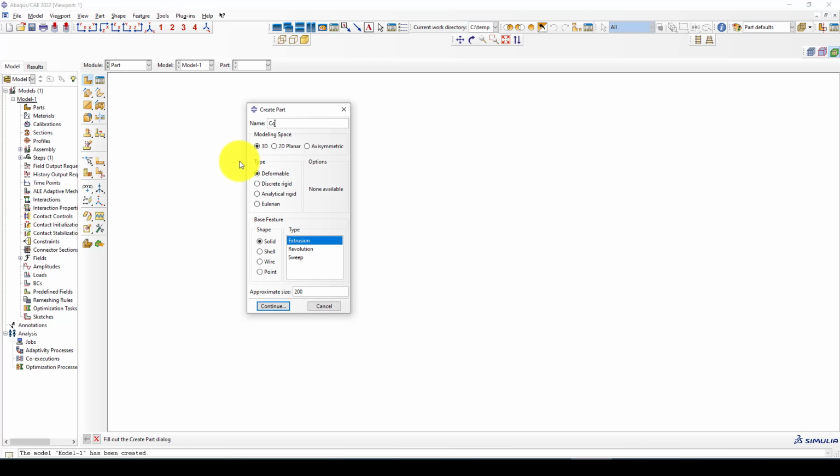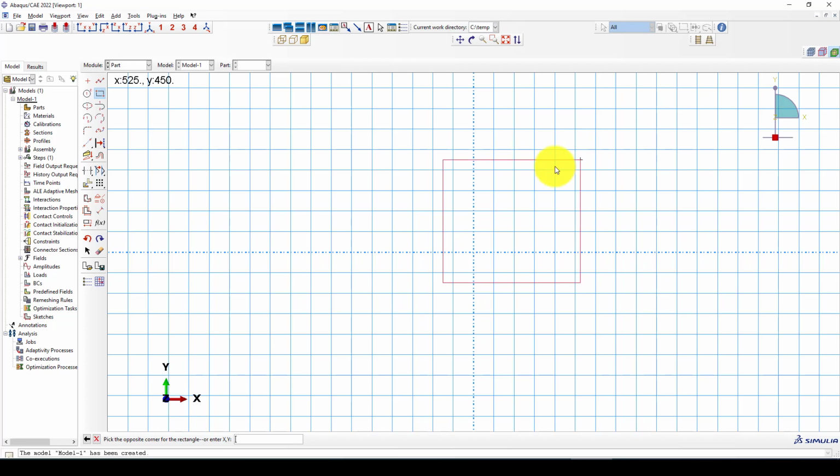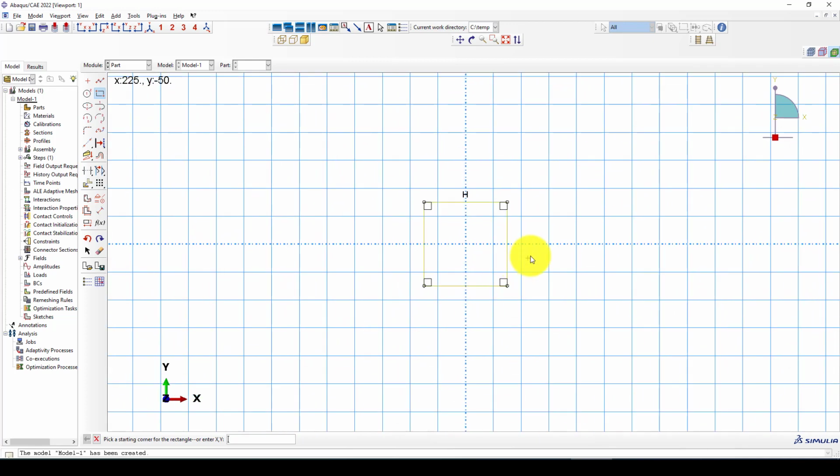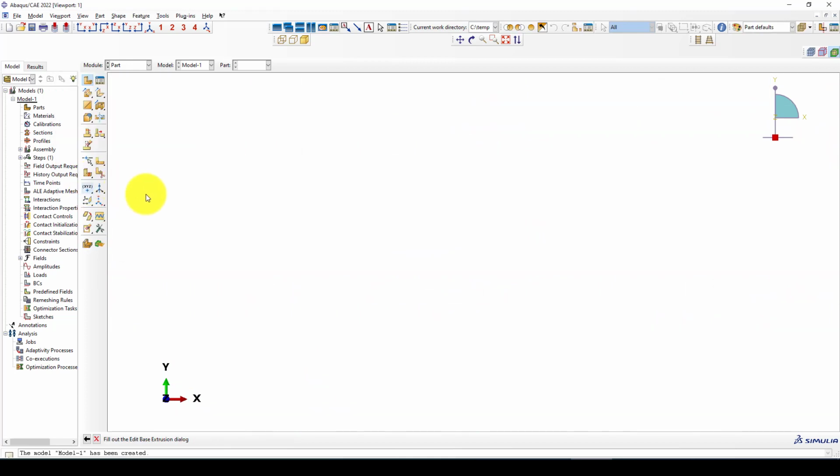The concrete part is the column, you can say 30 by 30, which is using a solid element. I can select a rectangle and give minus 150 and minus 150 for the X and Y direction. So now again, 150 positive and 150 positive. So the concrete section is created, and let me give the depth or height of 2 meters.